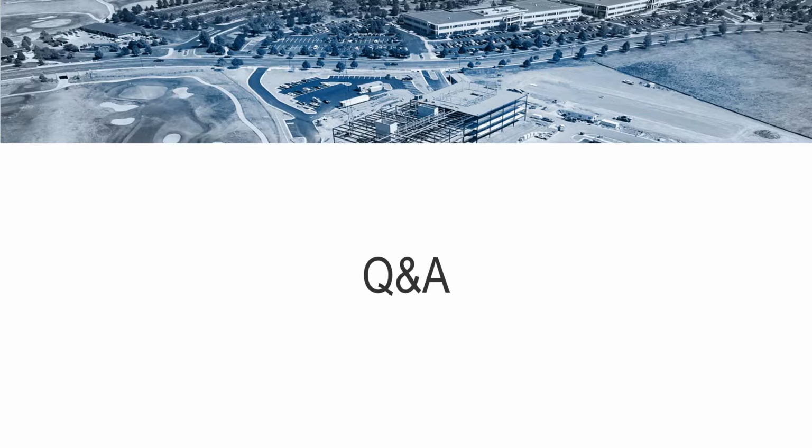Now, I would not do them on any standard or high resolution settings. The scanner has 3 settings: a low, a standard, and a high. Let me give a back overview of the scanner. The scanner is always collecting 500,000 points a second. As we increase the density of scanning from low to standard to high, all we're doing is slowing the scanner down, so it's collecting more dense data at a distance.